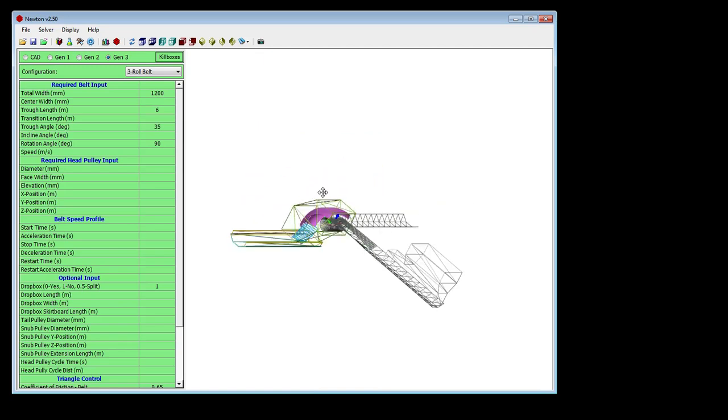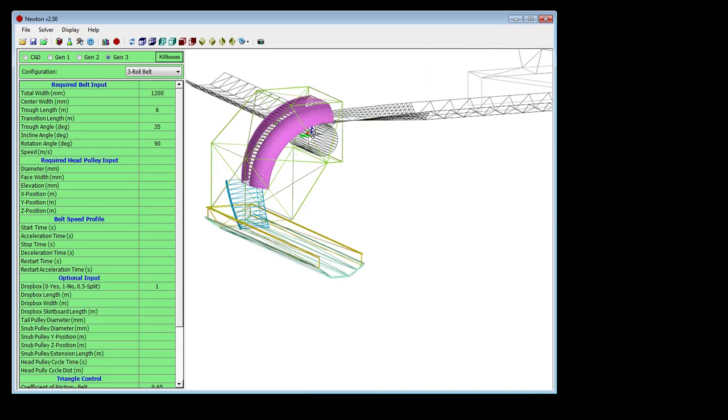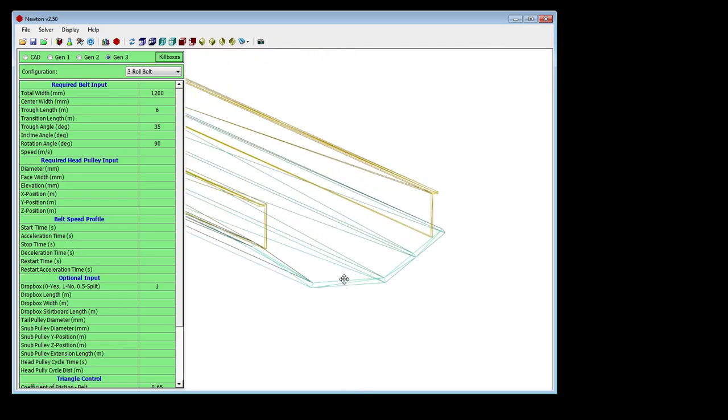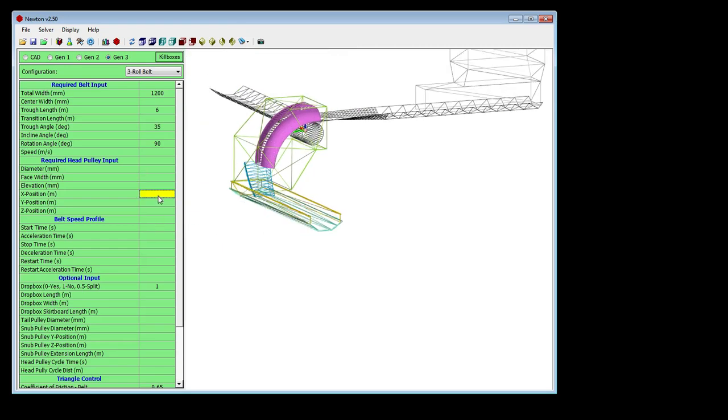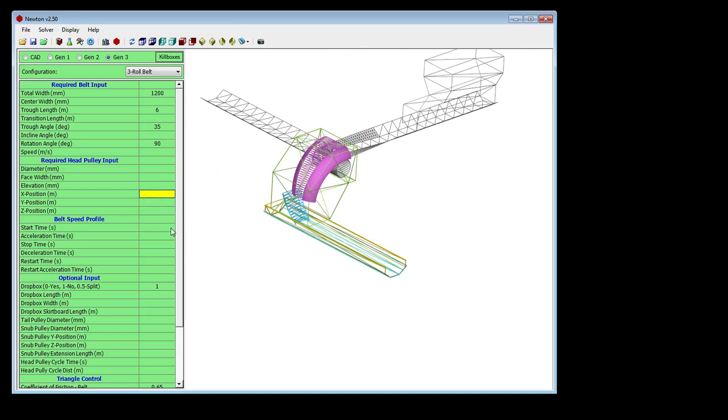So what you want to do is, in your CAD file, take a measurement from the origin of your CAD model to the front top center of the belt right there. And you want to take that measurement and punch that in the XYZ offset here. And so for this, those numbers are...